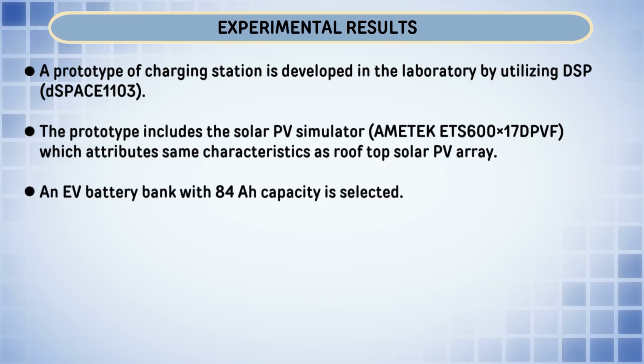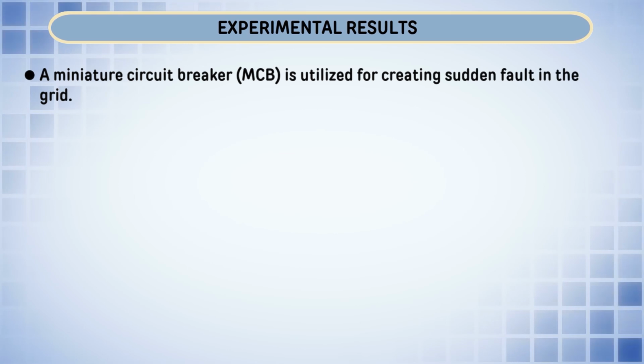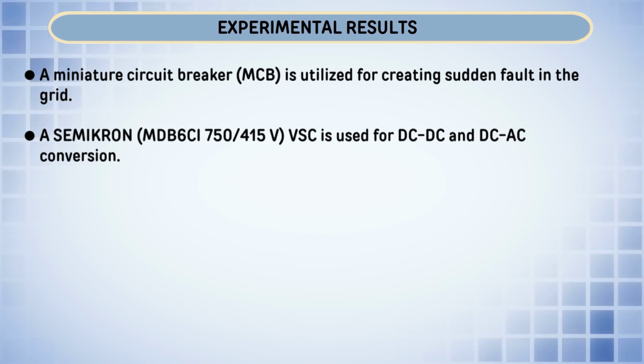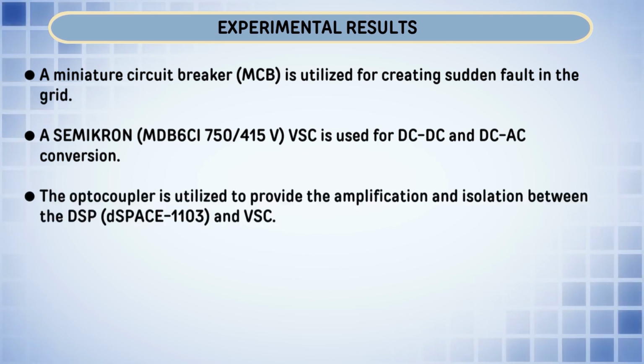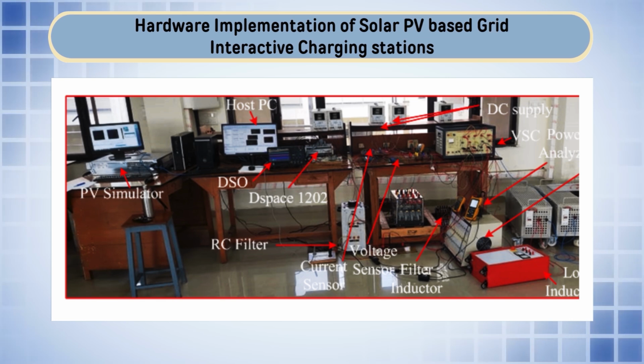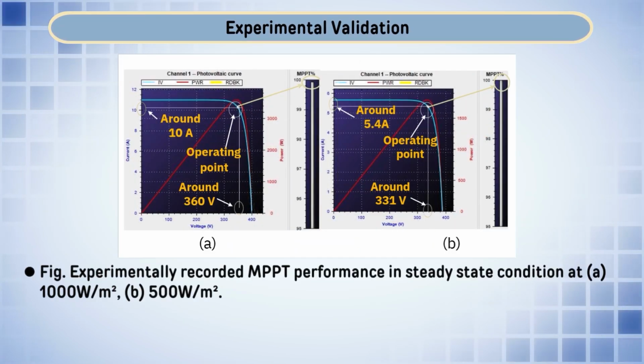So, we have certain components which are utilized to develop this charging station. At the right side you could find there are 4 batteries which are integrated in the charging station. They have different voltages and these batteries are integrated via bidirectional converters. We have a bidirectional converter here, a solar simulator is also selected as a rooftop PV array, and the power injection is taken care of by this renewable power which is supplied by the PV simulator here, and then as a control unit we have a dSPACE controller over here.